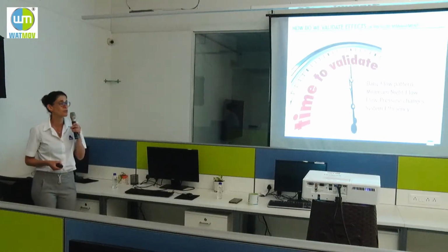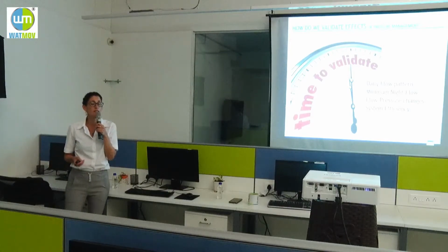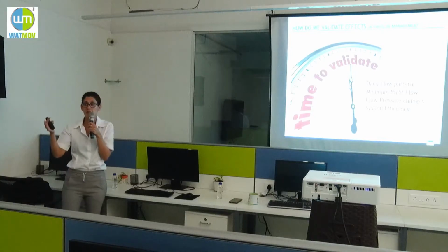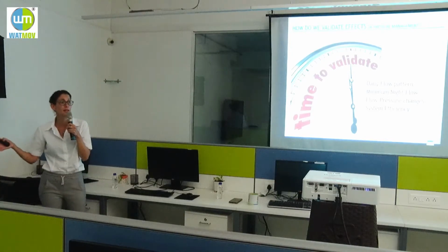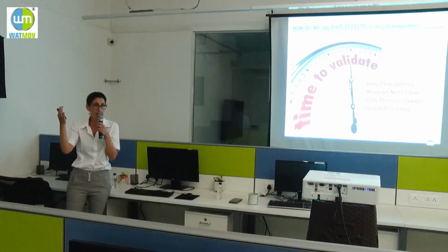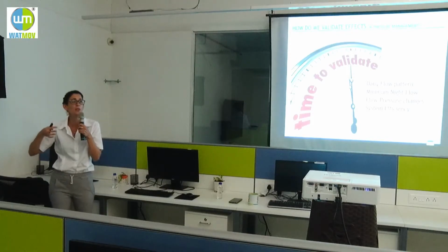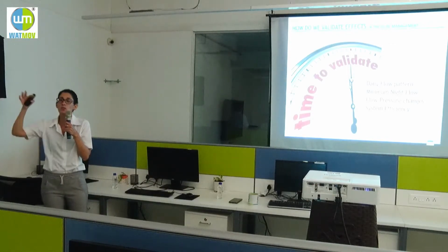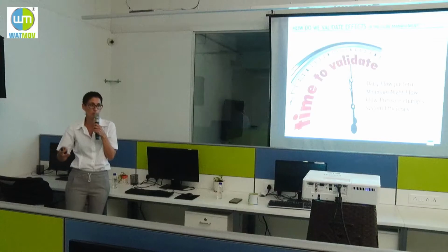When we talk about minimum night flow, this is very important, because when we apply our pressure management solution, we should compare the minimum night flow before the solution and after the solution. This gap will actually give us what we saved: how much water we saved, how much money we saved, how much we reduced the non-revenue water.